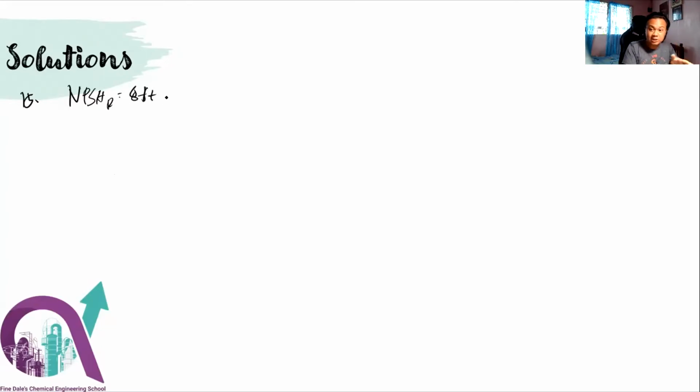So there are equations available in the Paris to get the NPSHA, the net positive suction head available. So you either add 5 feet or multiply by 1.35, equations 10-58 and 10-59, just pick. Choose whichever formula produces the larger NPSHA.